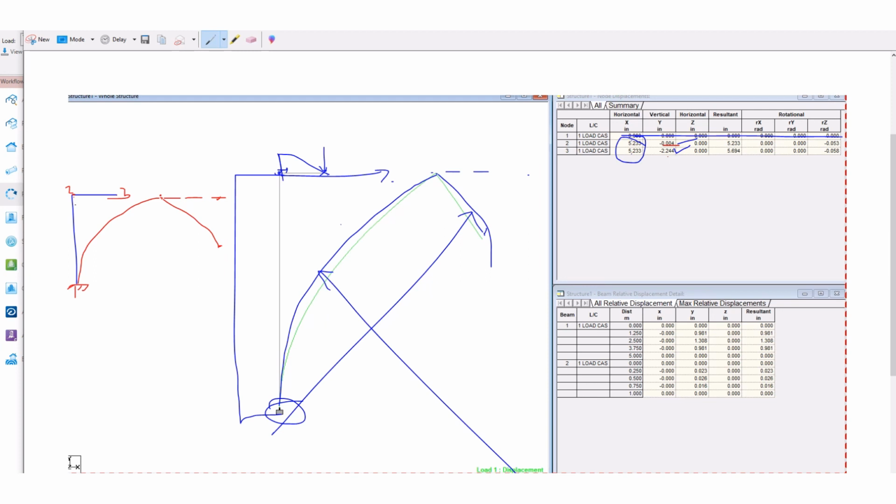This member is actually restrained, right? So that joint moved very little, 0.004 displacement. That's the Y direction. Y direction is the vertical direction. Here you see is the direction out of plane, where there is no force. That's okay. Then R is the rotation also. You can see this joint is rotated. Because of this force, this is rotated like this, no? So this is the rotation. This joint also rotated, 0.053 and 0.058. Okay, we will end this example.